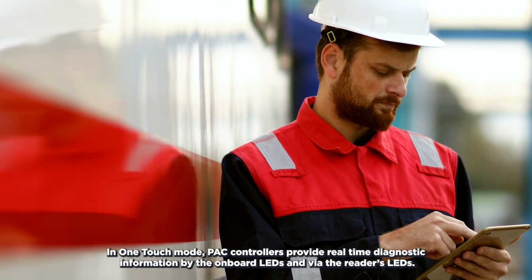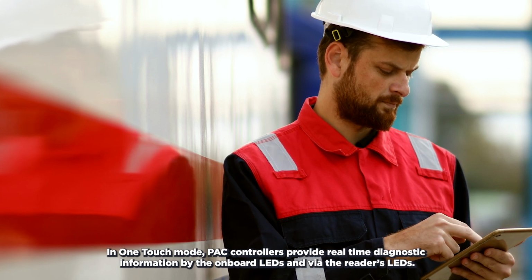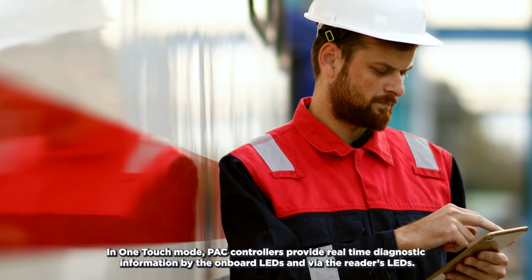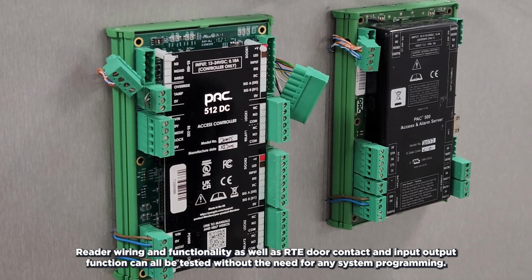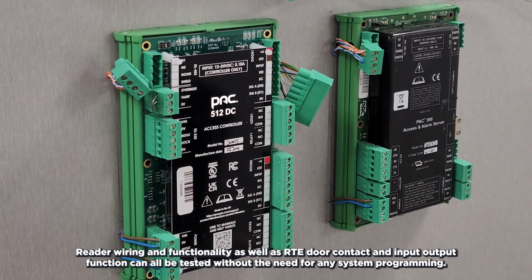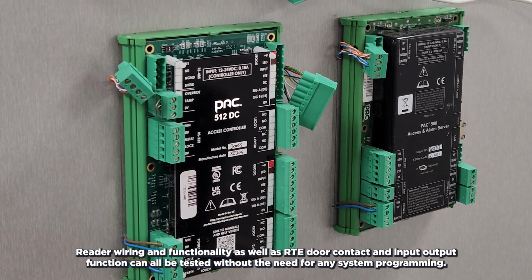In One Touch mode, PAC controllers provide real-time diagnostic information by the onboard LEDs and via the reader's LEDs. Reader wiring and functionality as well as RTE, door contact and input-output function can all be tested without the need for any system programming.